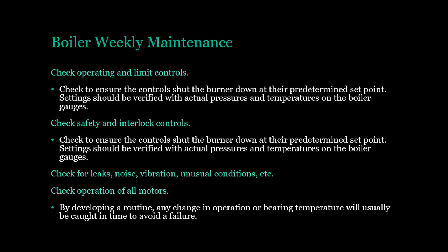Boiler weekly maintenance. Check operating and limit controls. Check to ensure the controls shut the burner down at their predetermined set point. Settings should be verified with actual pressures and temperatures on the boiler gauges.